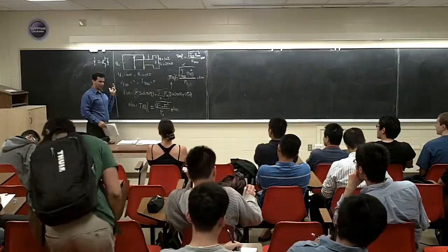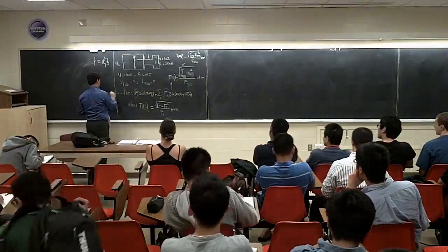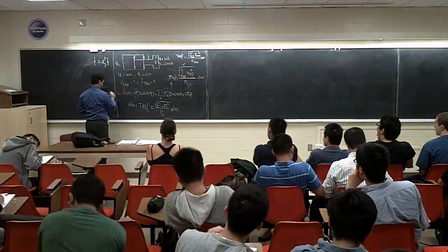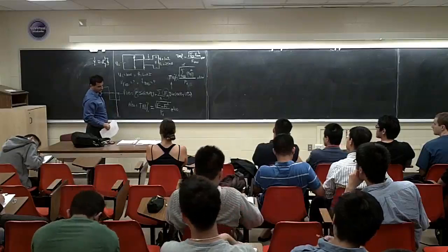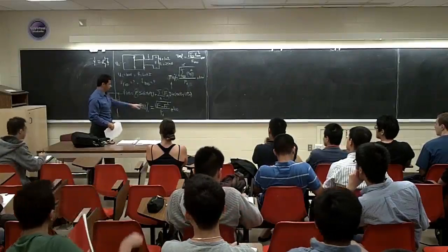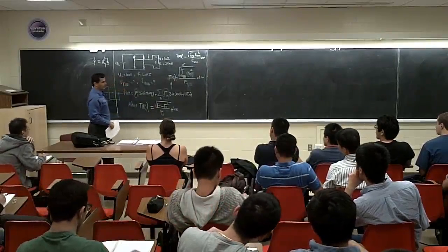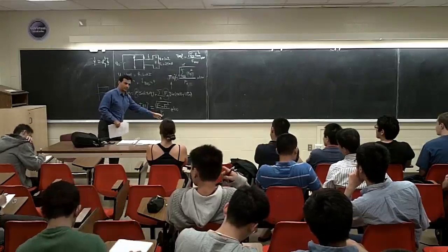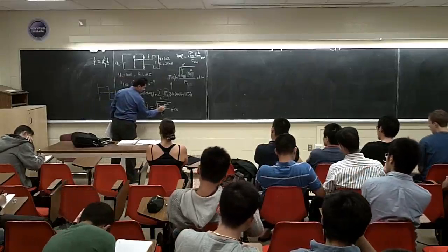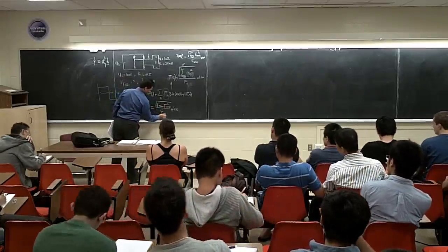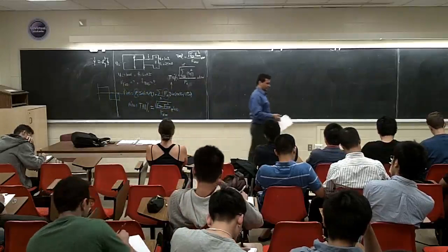So if I have a square waveform, look at here. If it's this one, I can calculate the RMS of this one easily. I don't have to go through the Fourier series and see how much it is. I can use this one minus the fundamental. I calculate the fundamental of this one divided by fundamental is going to give you the THD. Put RMS because most people do the RMS. F1 RMS. Now we know what's the definition of THD.